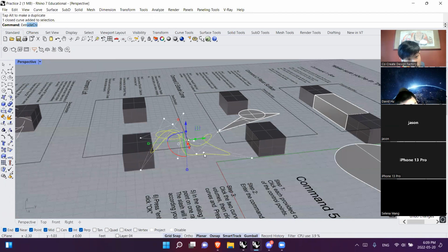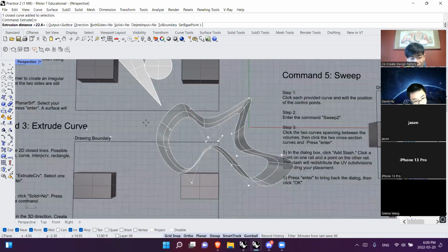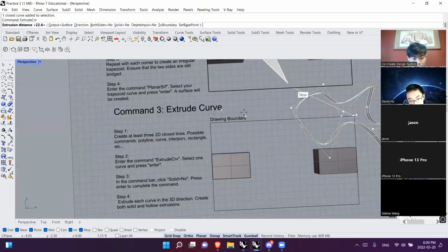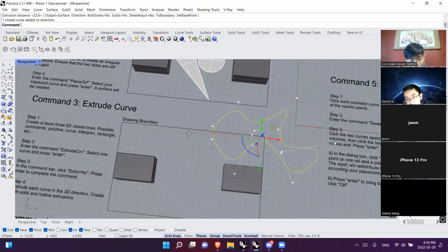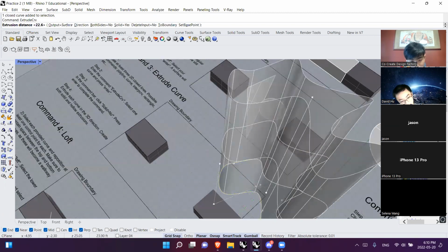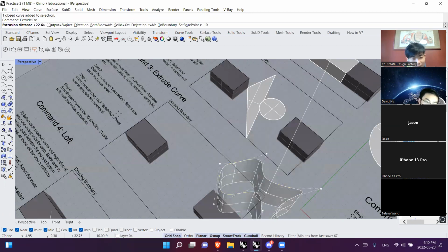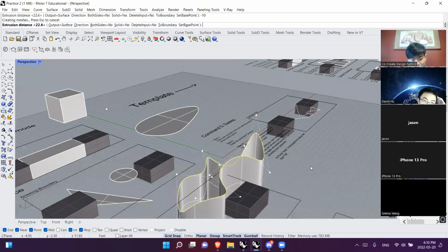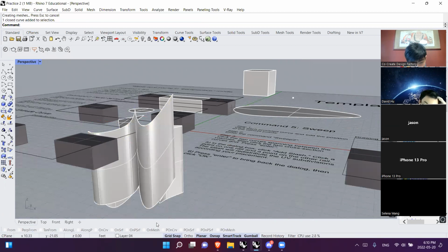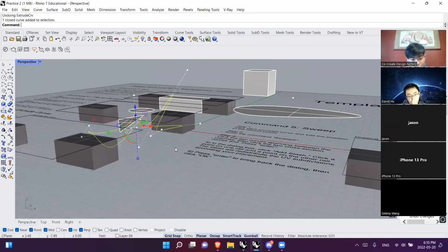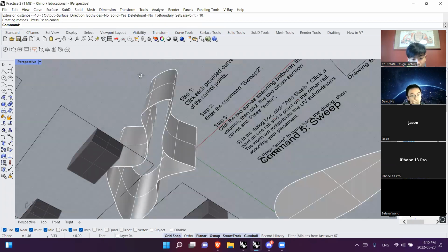And then we're going to use extrude curve. And it's still going to make a shape. Ooh, that's cool. This is because your command doesn't have 2D in it. Let's say extrude curve, make the distance like 10. Or if you wanted to extrude down, you can type -10. So like that, -10, enter. That's how it went down. So that's your original curve, and it basically created a surface down. Let's do it again, to like 10. Okay. So it kind of looks like that.